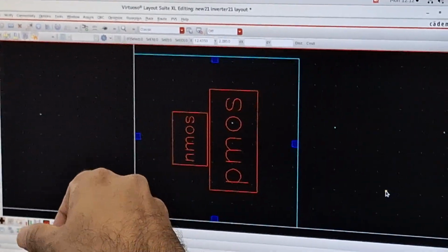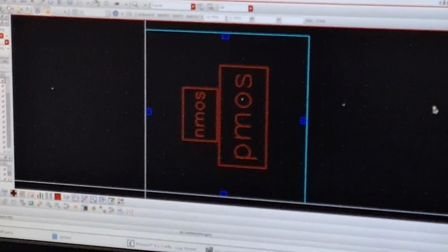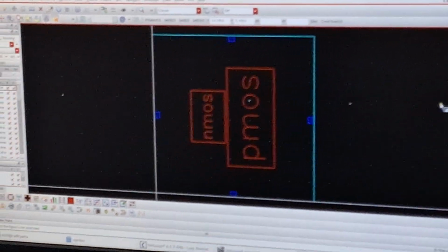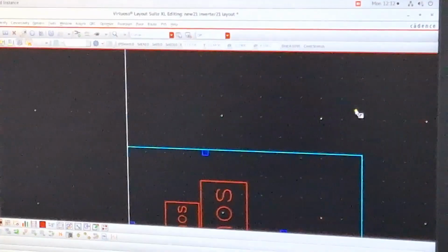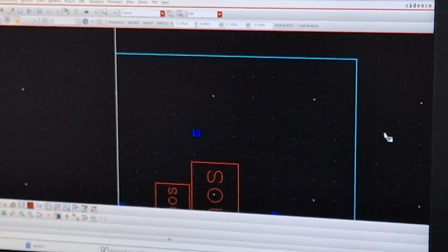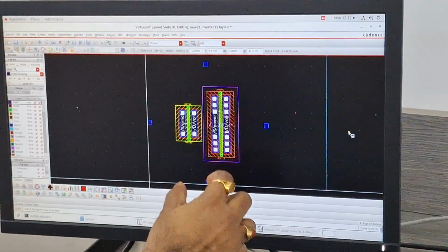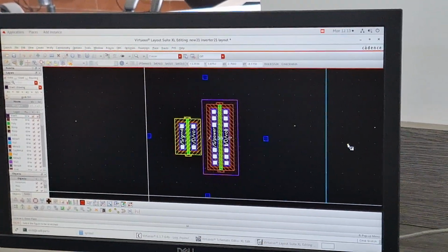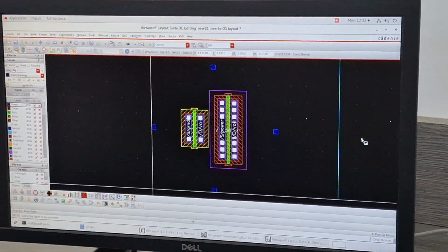Then this layout as it is can be done very well, but since you are new to the lab, you have to just extend this. Click on somewhere else, press yes, yes for stretch. Stretch this. Then click on Shift F. Shift F is for viewing your components. So what I did? Stretch, S and Shift F. Used the stretch and made the layout a bit bigger.